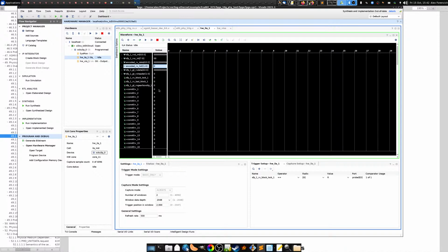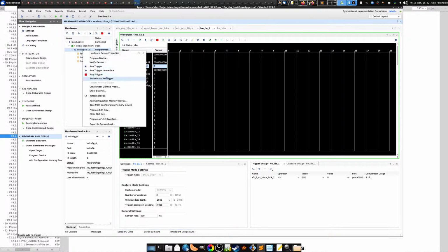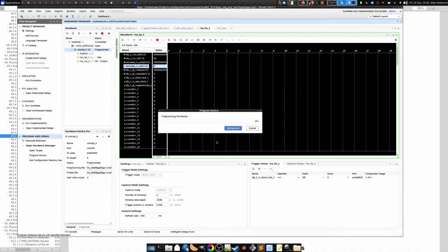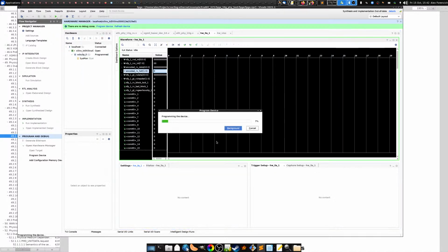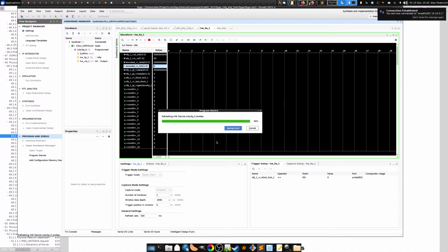All right, let's try that. So I think what's happening here is, since I wired up both PHYs instead of just one, which probably would have been a smarter thing to do, basically both PHYs are getting reset, or both transceivers are getting reset. Rather annoying. All right, let's see.